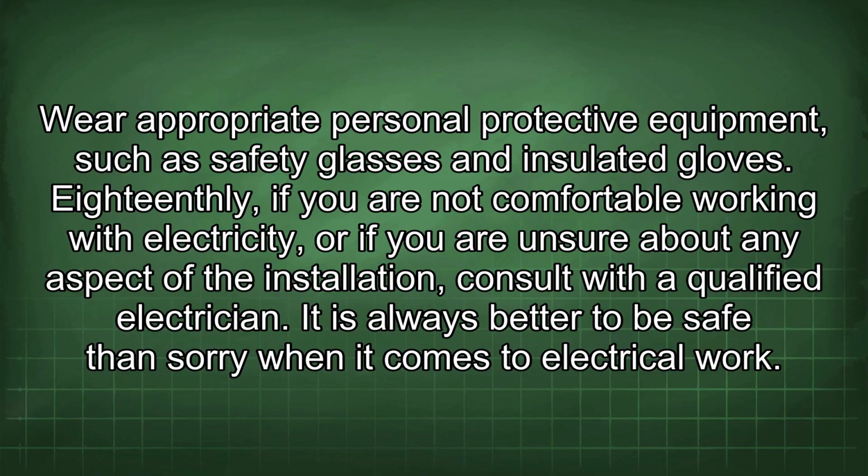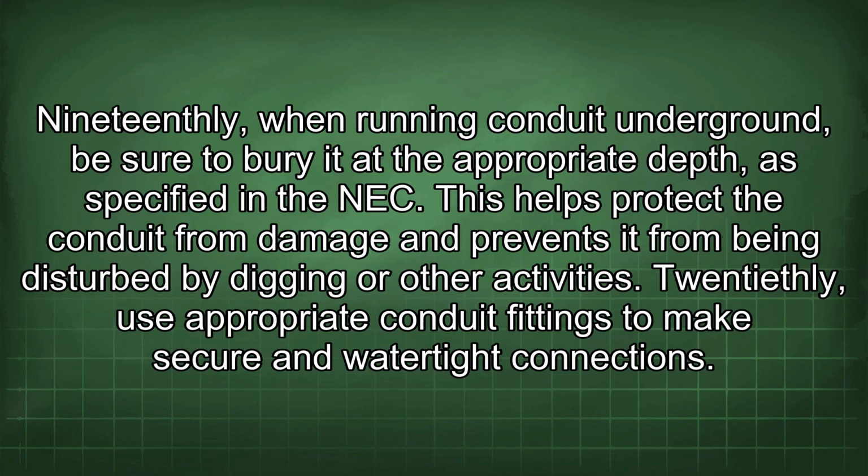18thly, if you are not comfortable working with electricity, or if you are unsure about any aspect of the installation, consult with a qualified electrician. It is always better to be safe than sorry when it comes to electrical work. 19thly, when running conduit underground, be sure to bury it at the appropriate depth as specified in the NEC. This helps protect the conduit from damage and prevents it from being disturbed by digging or other activities.